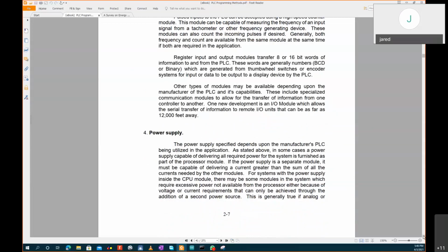So that when the power supply is the one that fails, the PLC is still intact. Your phone is one unit. It has the battery, the power, the screen. If the screen goes off, the whole phone is affected. But the PLC is made industrial in a way that if the power supply fails, it only fails on its own, totally isolated from the PLC. If one of the input modules fails, it fails alone. The PLC, the main processor, the main brain is still intact. You just replace the module and life goes on.